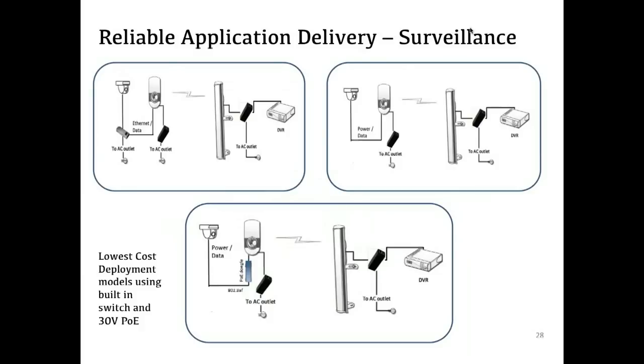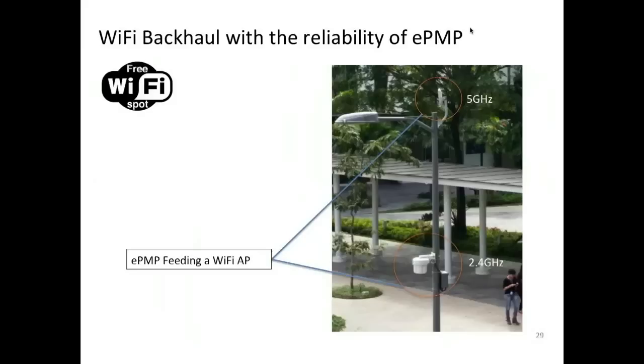The second port of the ePMP CPE also has a 30-volt PoE out. And then last but not least, we have some accessories in development where that 30-volt PoE can be converted to a 48-volt 802.3af. The conclusion here on the surveillance system is we're giving you not just a software benefit, but there are some hardware aspects that give you the advantage of deploying a low-cost video surveillance solution.